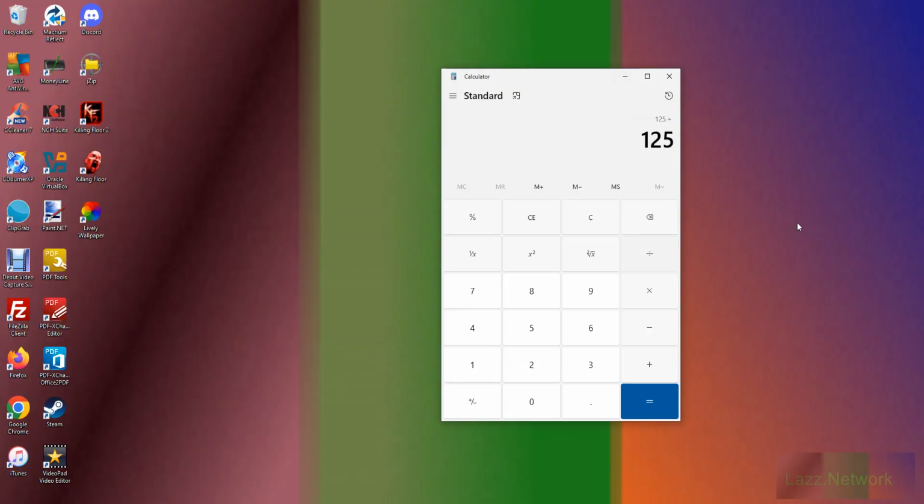Let's figure that out. 125 divided by 1,000. It's 12.5%. I can't believe I couldn't do that in my head. So understand, out of that 1,000 milliliter cylinder, only 12.5% of that is your sodium hex mix. That is your 40 grams to every liter that you're going to add to your soil slurry solution. Then you add the water. But even with that kind of concentration, it's still going to displace your hydrometer because it's very sensitive to particulates.